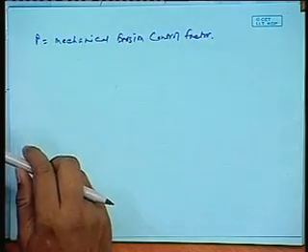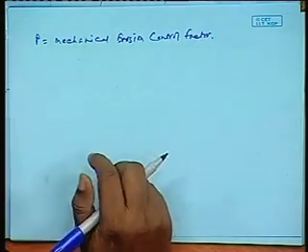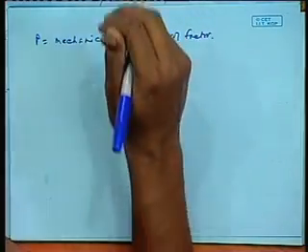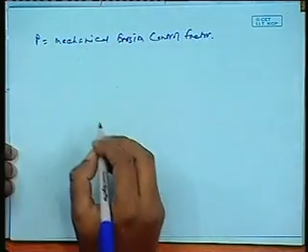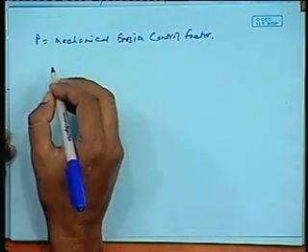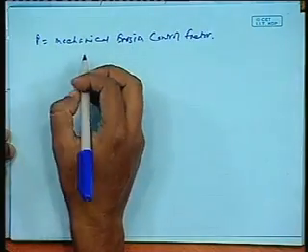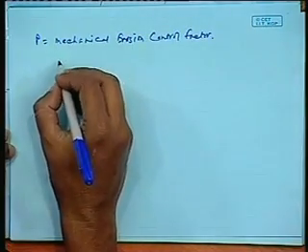Okay. Now, if we investigate, trying to understand this soil equation and the factors that you can see here: R is the rainfall factor, K is the soil erodibility factor, L is the slope length factor, S is the slope gradient factor, and C is the vegetation factor. P is the mechanical soil erosion control factor. What is interesting to observe here is how this equation has been constructed. The most important part of the equation is R and K.